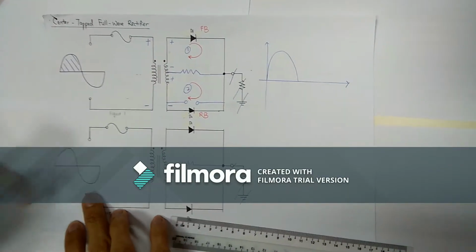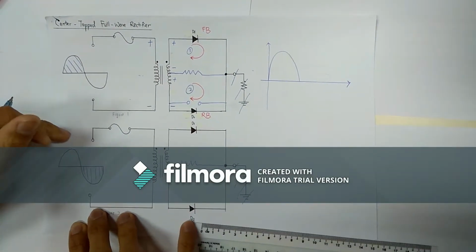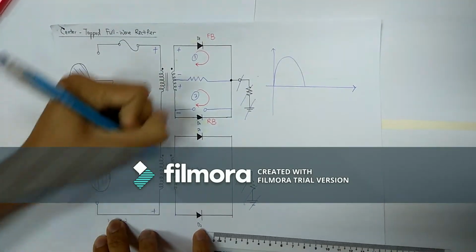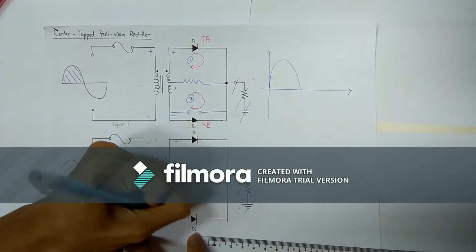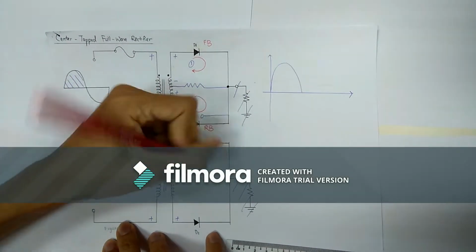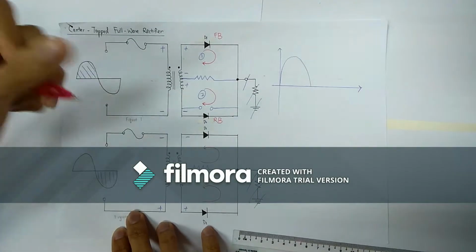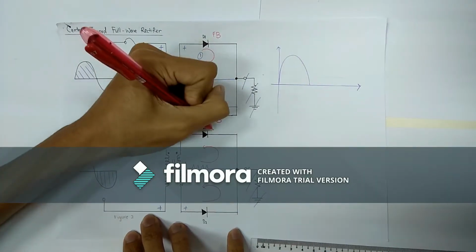At the negative cycle, the current will flow from the positive terminal to the negative. So at this condition, D1 is acting as reverse bias, while diode 2 is acting as forward bias.